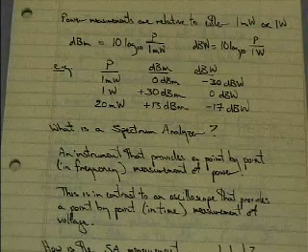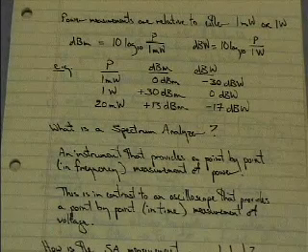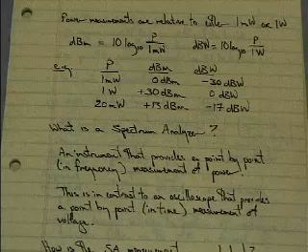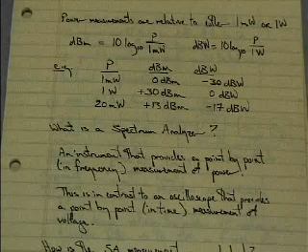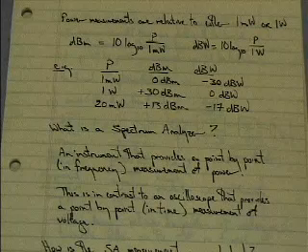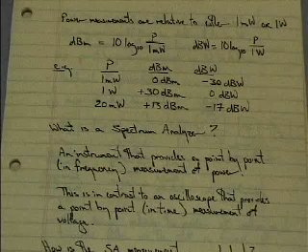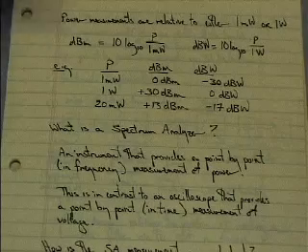So when we're talking about power, we need to make sure that we have either dBm or dBW. If we're talking about a ratio of powers, for example, a loss in a system or gain in a system, then the units are going to be dB, no M on it and no W on it.